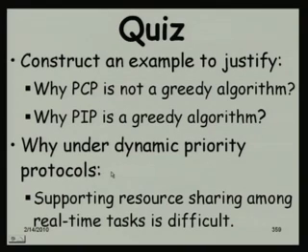Inheritance related. Suddenly the priority will change. Yes. And then we don't know. Suppose we have assigned a lower priority. Exactly. So, there will be too many inversions because implementing a protocol to minimize the inversion is very difficult, because the ceiling value itself changes dynamically. The task priorities change and the ceiling values change, and we can't think of a protocol. I mean, nobody has thought of a protocol which can be used to reduce the inversions. So, it is unusable when the tasks have to share critical resources.